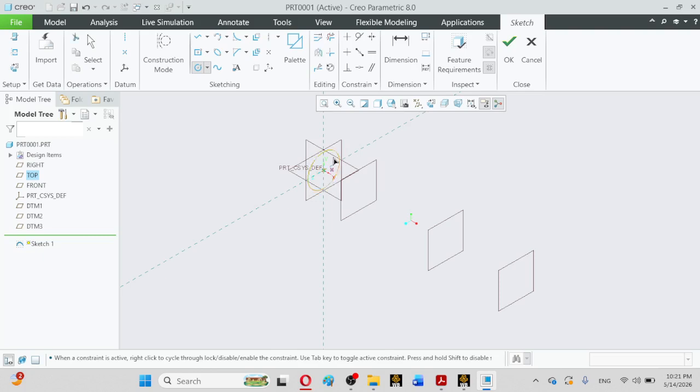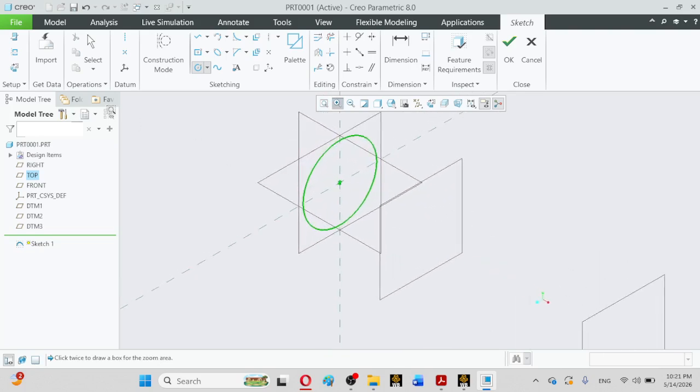Again, you will have to divide the circle into as many segments as the section which contains the maximum number of segments. For example, this rectangle consists of 4 segments, so this circle must be divided into 4 segments.